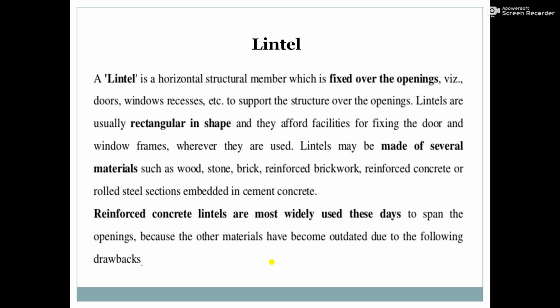Now the next point from the chapter, that is the lintel. The lintel is a horizontal structural member which is fixed over openings, doors and windows, recesses, etc., to support the structure over the openings. Lintels are usually rectangular in shape and they afford facilities for fixing the door and window frames wherever they are used. Lintels may be made of several materials such as wood, stone, brick, reinforced brickwork, reinforced concrete, or rolled steel sections embedded in cement concrete.